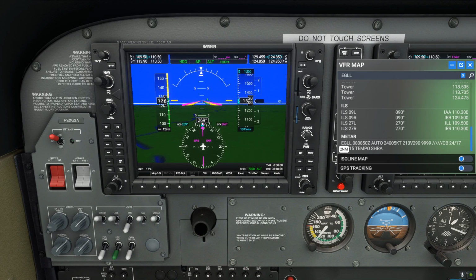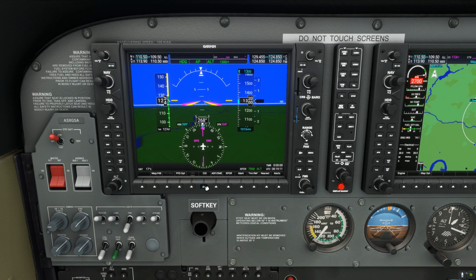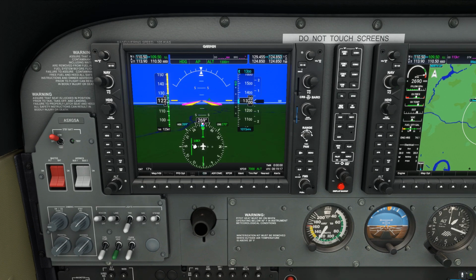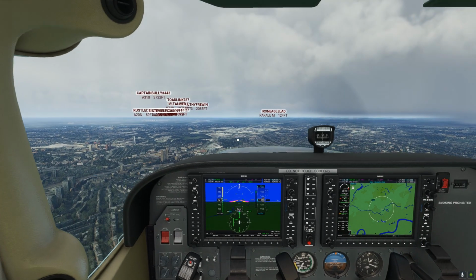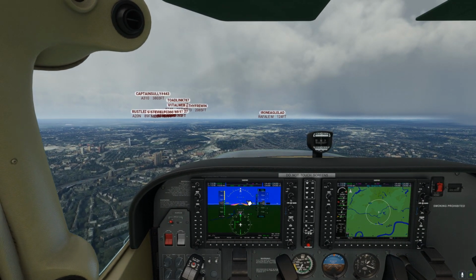05. And that's the ILS for runway 27 left. I'm going to swap that, and we should see the identifier come up for Heathrow Airport 27 left, which is correct. Going to change my CDI to Loc 1. Remember, I've covered this in other videos, and it's going to show us the course deviation indicator here, where we want to be lined up for that runway.